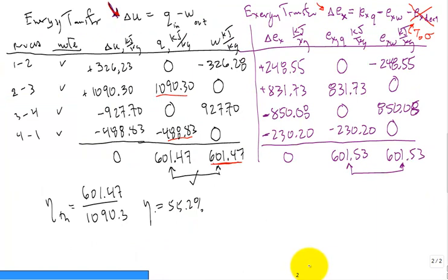What is the mean effective pressure? Okay, well, what is the mean effective pressure? Well, if you multiply the mean effective pressure by the displacement volume, the specific volume that's being displaced, V displace, you'll get the W net. Okay, so to calculate the mean effective pressure, I just divide by displacement, clean this equation up a little bit.